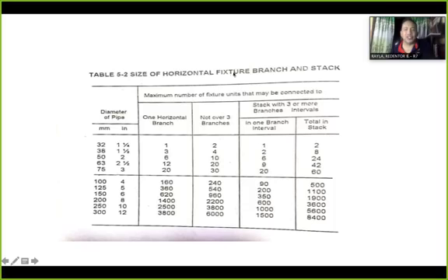For example, you have 3,800 fixture units. So one horizontal branch, no? In one horizontal branch, there's a lot of connections: drains, water closet, a kitchen. So everything connects into one line, no? So that's 3,800. So what is the size of the horizontal? Here, 12 inches. Okay? So that's how big, because there are also a lot of fixture units connected to that line, to that Y.